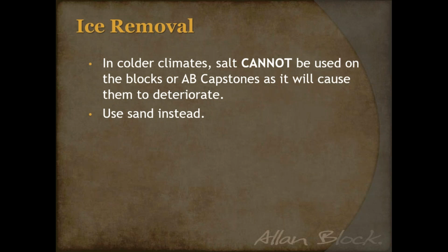Any concrete product, I don't care if you're talking a sidewalk or an Allen block or a paver, they don't like salt. That freezing and thawing will deteriorate concrete over time. I mean, look at what those of you that live in northern climates see with salt on the roads. What do you think all these potholes are from? That freezing and thawing condition is really hard on hard surfaces like concrete and asphalt.